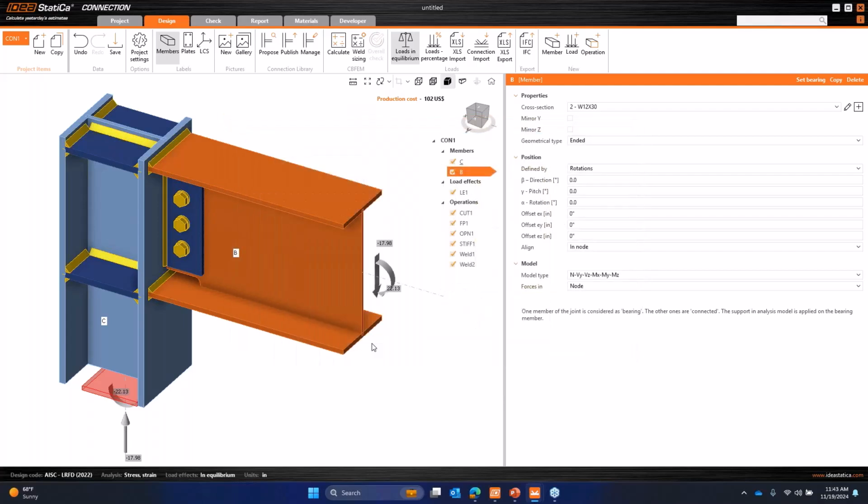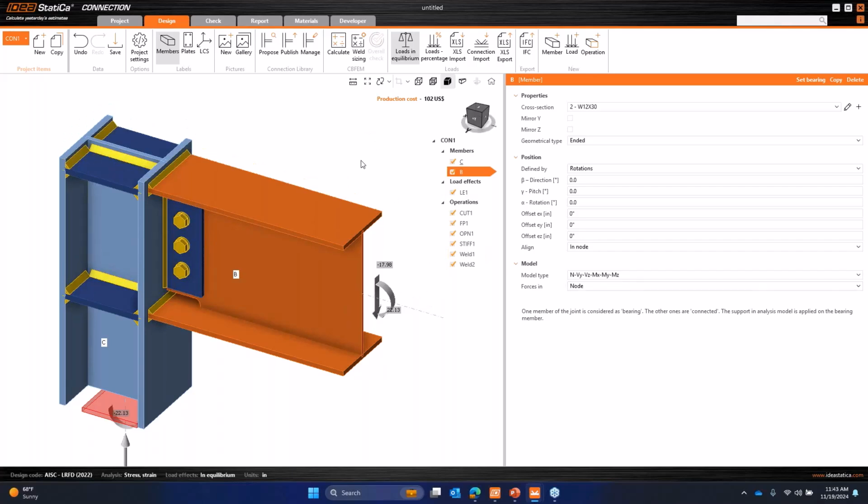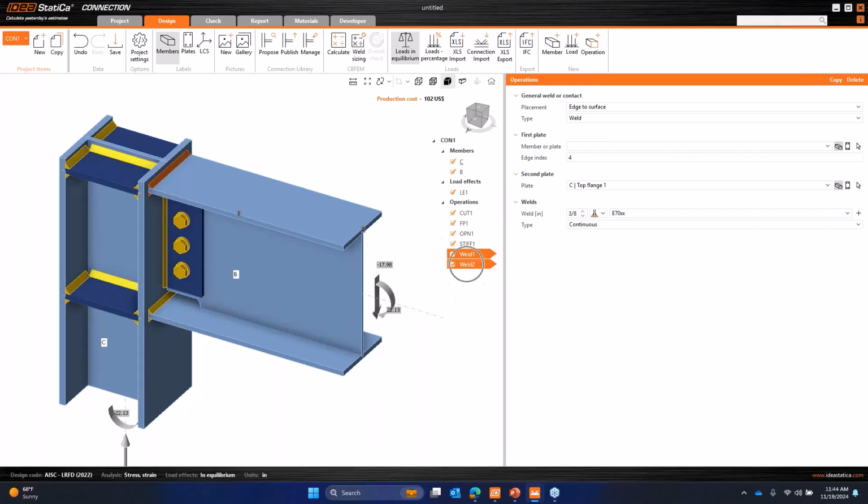So with this, we basically covered some of the other smaller improvements, which are the measuring tool. Again, you can find this measuring tool on the very first symbol from the left. Just click on it, select either your corners, edges, or surfaces to be able to measure different distances. To exit, just press the escape button and you will be able to go back to normal. The second one was the multi-select, multi-edit operations, meaning you can multi-select different operations. If they have similar parameters in common, you will be able to adjust them.